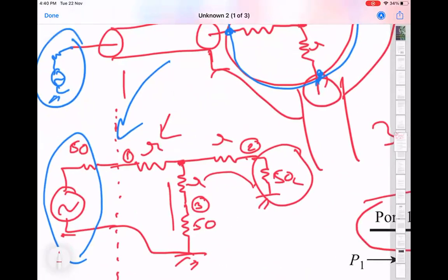this circuit here, for ports 2 and 3, I have terminated that transmission line with a 50 ohm resistor so that we are terminating with a matched port. Because remember that when we used to compute the S matrix, you have to make sure the boundary conditions are all correct, right? When somebody says it's matched on port 1, it's assumed, in this case for a 3-port network, that port 2 and port 3 have already been terminated with a matched load. Only then the port 1 will be matched, and vice versa, for all the same ports.